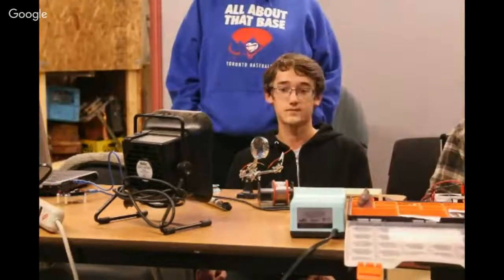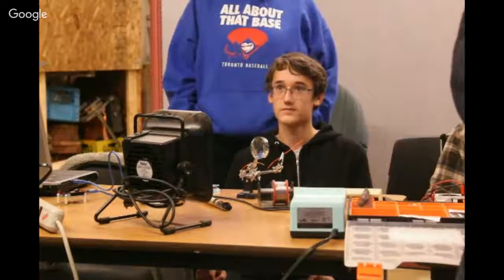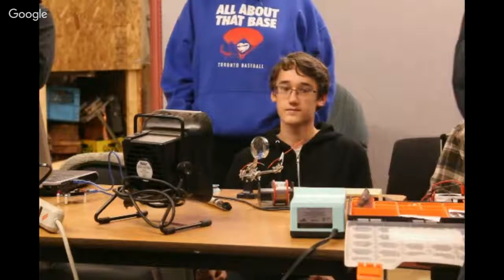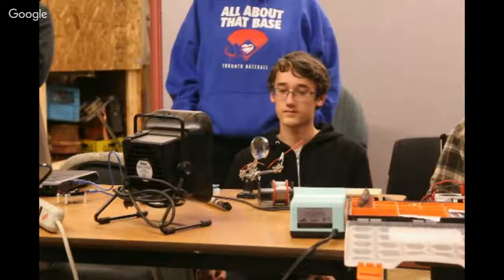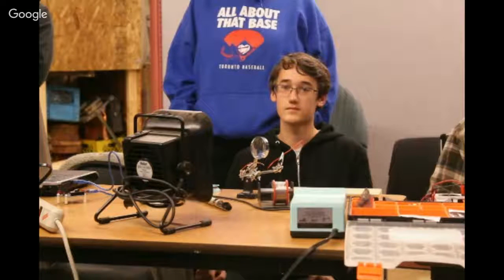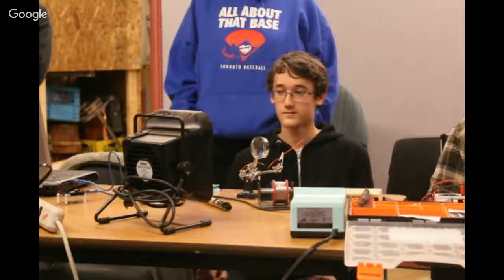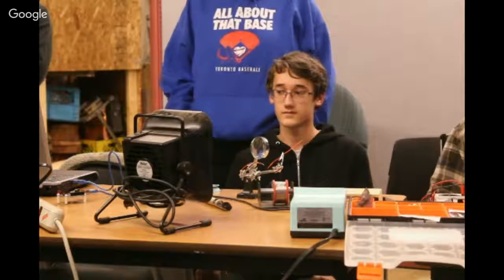And so that is actually a desoldering gun, because it'll heat all of the pins up so you can pull the chip off all at once. This is great, it makes it a lot easier, but if you are using that, be really careful about not overheating the chip if you want to reuse it. It's a lot harder to control the heat coming off a heat gun than it is individual solderings.